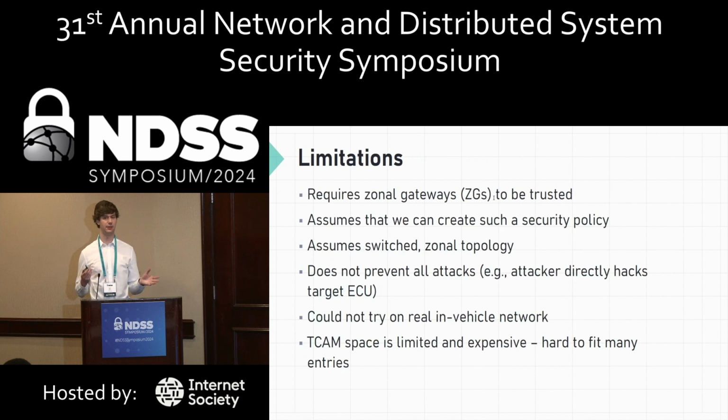Of course, this method has many limitations. One, it requires that the zonal gateways are trusted. We can create such a security policy, although I'd argue that doing so is just good to do anyway. And that you have this topology. We don't prevent every attack, and we couldn't try it on a real in-vehicle network because we didn't have the money. But the biggest one is that TCAM space is limited and it is expensive. However, I do think that with enough work, the distributed nature of our system would let you partition the security policy into a very reasonable amount of TCAM space.